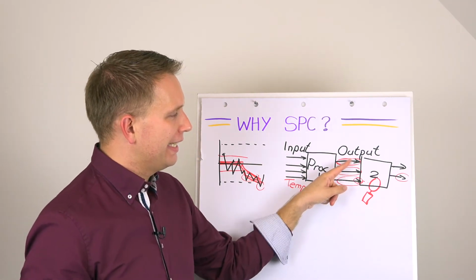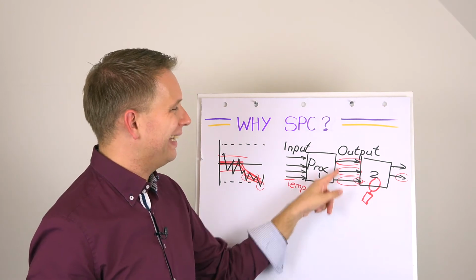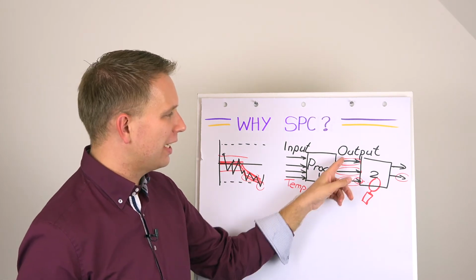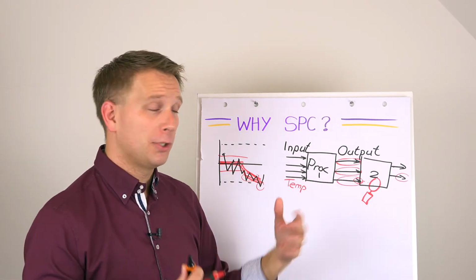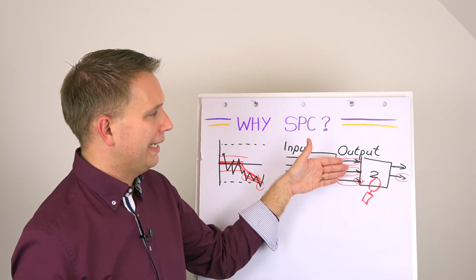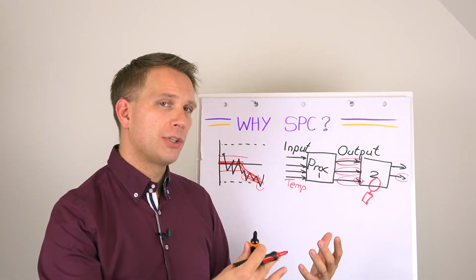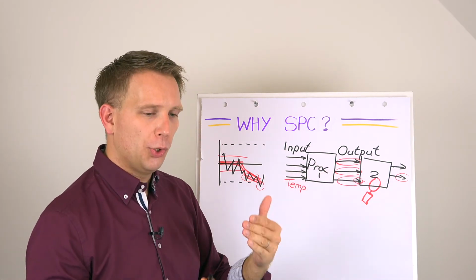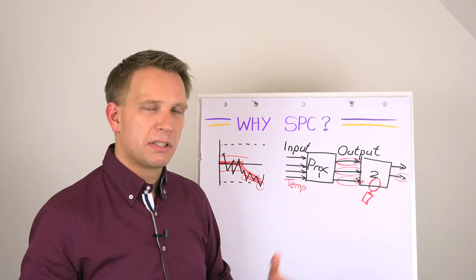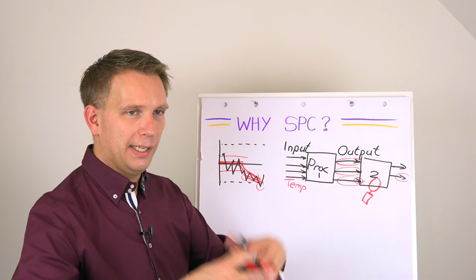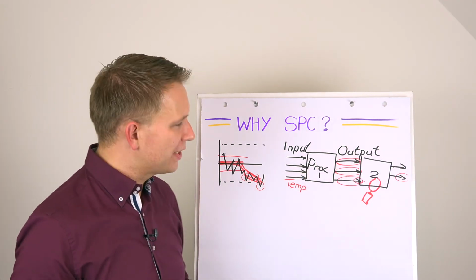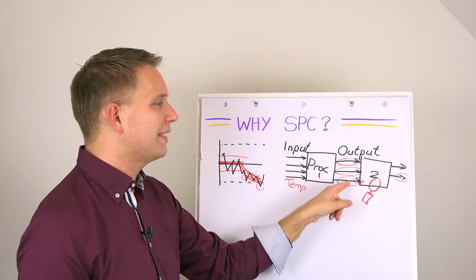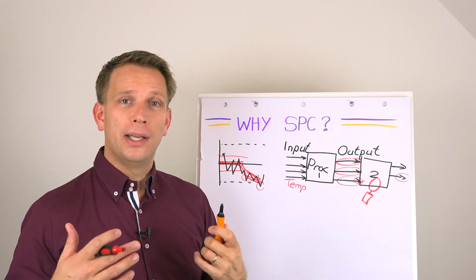But these are important inputs for your second process, and they are outputs of your first. It's likely that you don't have very strong specification limits for these, that you may be able to correct things. So when the weight is a bit lower, then maybe during storage it will attract some moisture, or here with the first check weigher, you know to set the machine a bit differently and slice 9 parts out of it instead of 10, and then again your end slice product has correct weights, things like that. So we very often correct our own internal products, but these are golden to also put your statistical process control on.